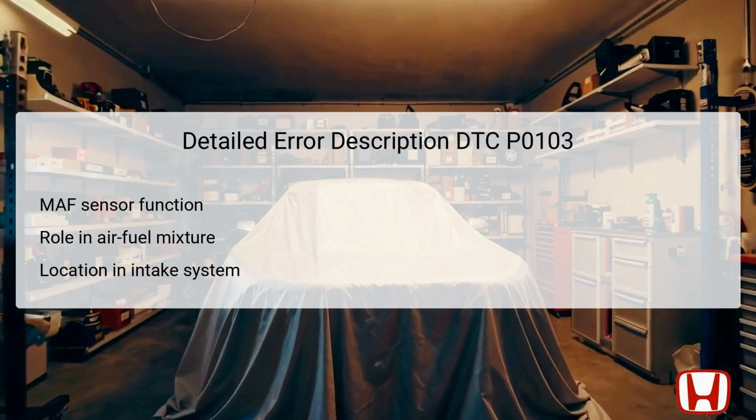The MAF sensor plays a vital role in engine performance by measuring the mass of air entering the engine. It ensures that the engine receives the right amount of fuel to maintain an optimal air-fuel ratio for efficient combustion. This sensor is located in the air intake system just upstream of the throttle body in the Honda Civic 2011 to 2015 models. High voltage readings at the MAF sensor, indicated by DTC P0103, suggest potential issues in the sensor circuit, which may cause improper air-fuel mixture calculations by the engine control module, ECM.